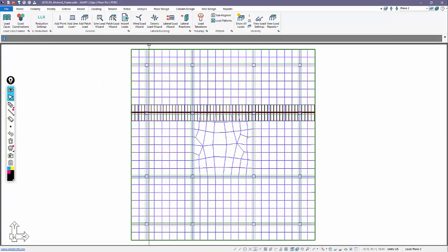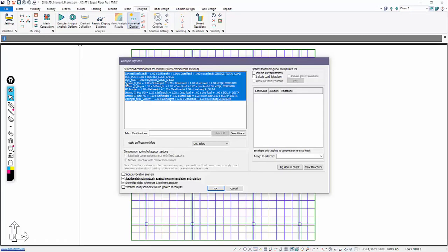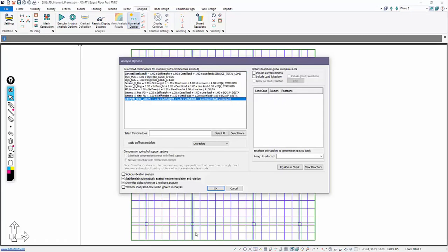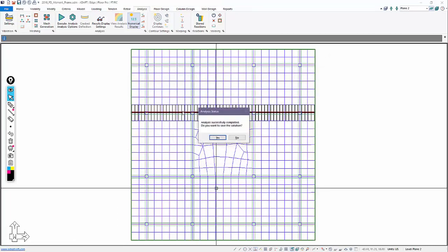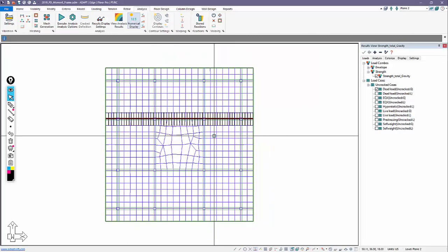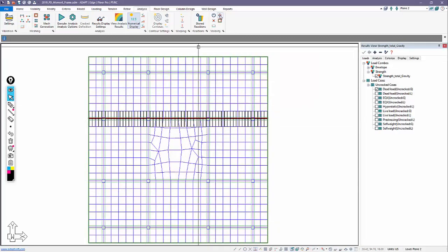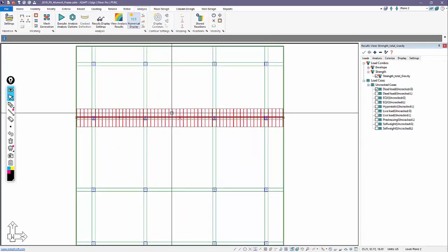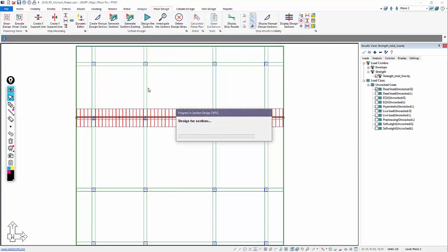Once the load combination is completed, we'll come back to analysis, and we're going to execute. We'll execute for that one strength combination here. We'll go ahead and select OK to run the model. Select yes to save, and then we're going to design the strips. Now I want to turn off the view of the elements, so under the visibility analysis ribbon we can turn off the shells there, and I'll select this strip, and we're going to design the design sections.